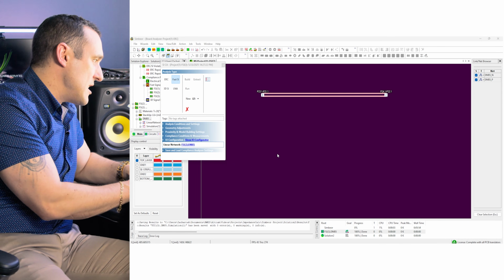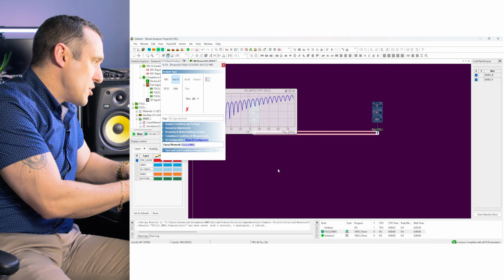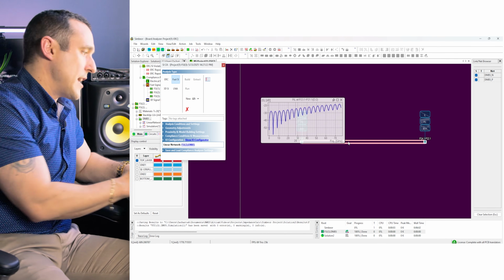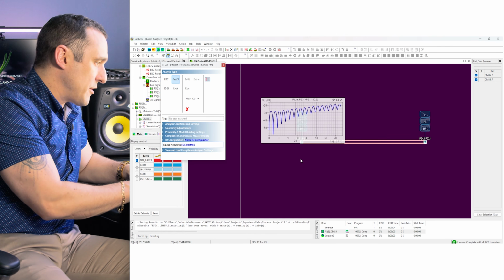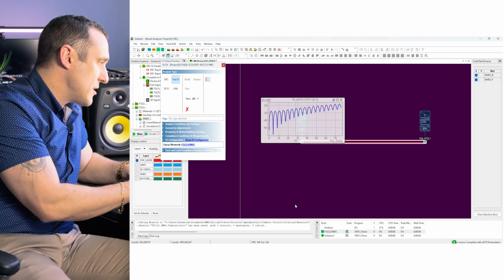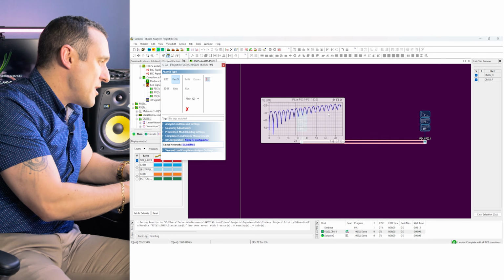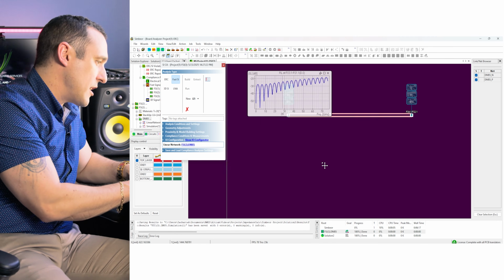And we can then see what the S parameters are for these microstrips. So the reason I bring this up is just for a comparison with what we're going to look at in the case with the length tuning sections. So here you can see that we're about negative 30 dB up to about, let's say, negative 20 or about 20 gigahertz, and then we rise up to about negative 20 dB into the 40 or 50 gigahertz range.